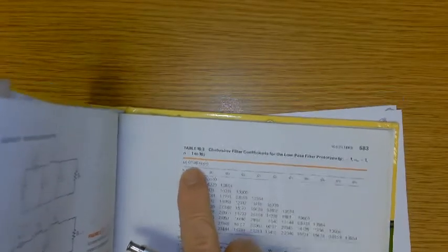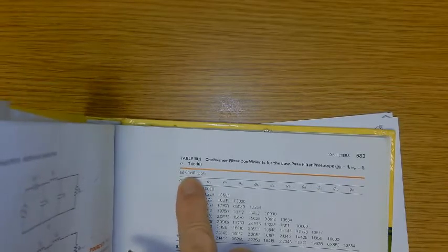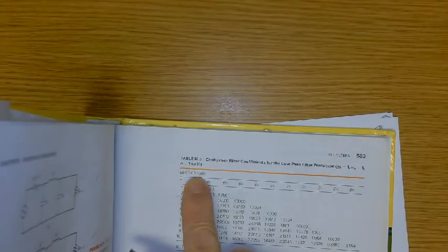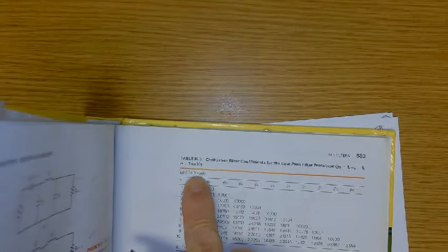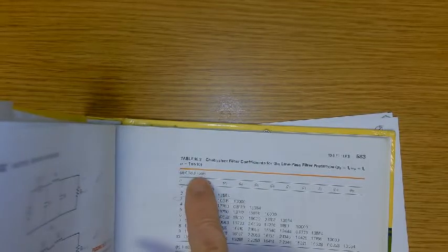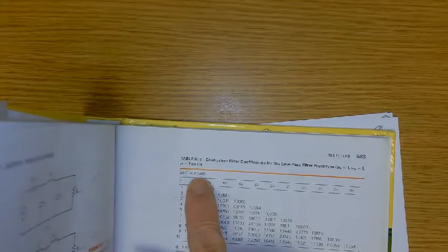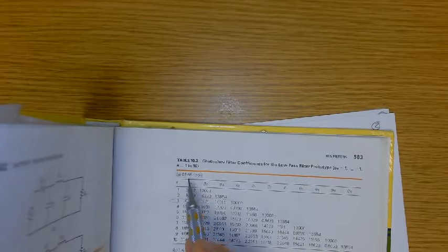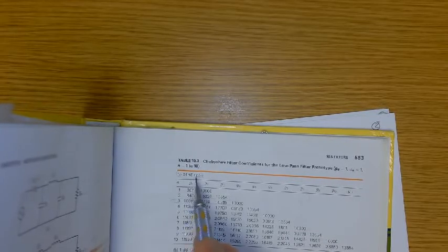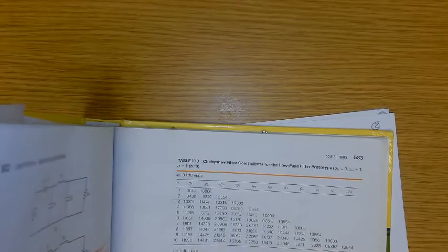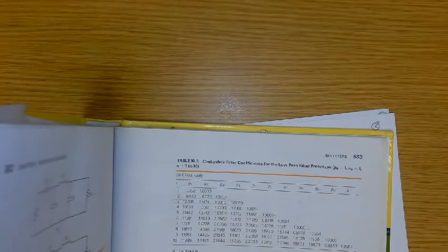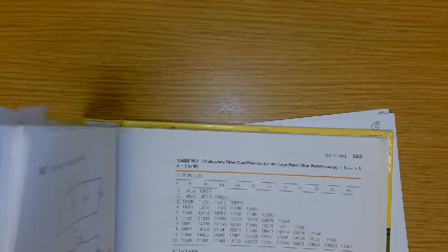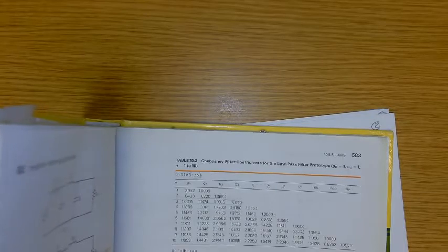So 0.1 dB ripple means that I just don't allow very much change in the pass band, or stop band, or low pass or high pass. But here let's think in terms of low pass, and we're going to observe how to change that into high pass. So we just don't allow much ripple in the pass band. Here we're going to allow a little more ripple with these numbers, and then finally we're going to allow more ripple still with these numbers.